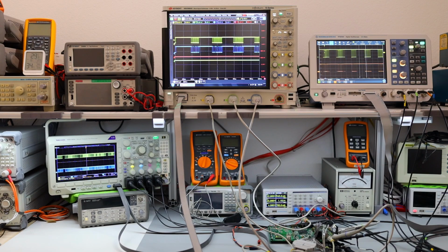So let's take a look at how to first set up a signal acquisition for I2C. All 3 oscilloscopes are currently connected to the same signal, and they are all updating their displays in the default mode. I have not optimized them to capture a specific waveform, and they are all just capturing and trying to find an edge trigger and the most optimal trigger for this situation. Let's get started, and I'll show you first how to set up a trigger and clean up this jittering waveform, and then we will take a look at how to set up a decode, because currently, even if you set up a decode, it will work, but it will be too slow or unreasonably flickering to be able to find anything useful.